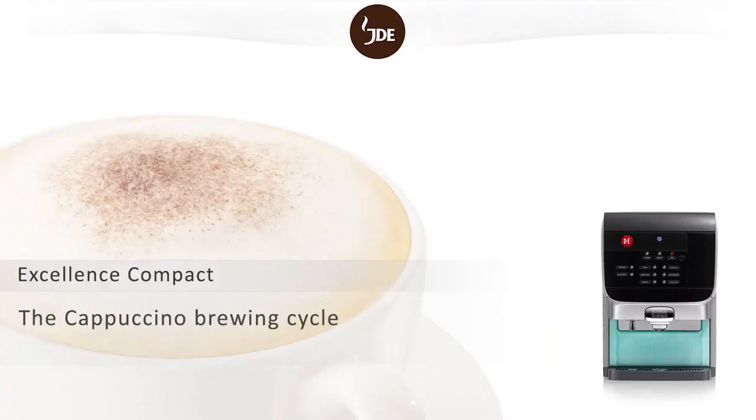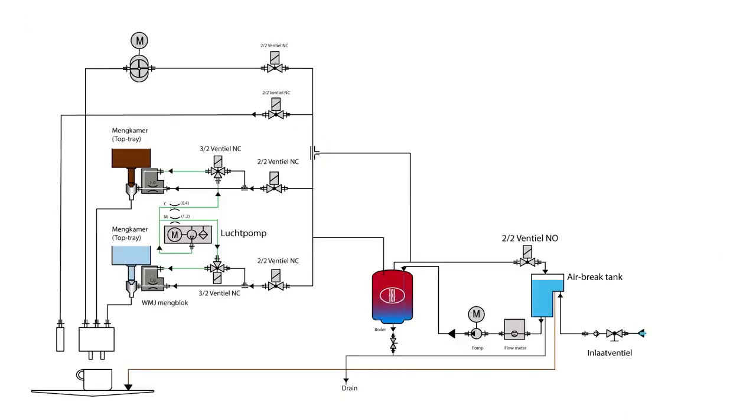The next step is to describe the brewing cycle of various drinks step by step using the water flow diagram. After the cappuccino button is pressed, the sequence is as follows. The pump is switched on and water is pumped into the boiler. Hot water in the boiler flows into the system. The flow meter measures the required amount of water. A small amount of hot water flows into the tubes and back into the boiler. This recirculation serves to preheat the system.